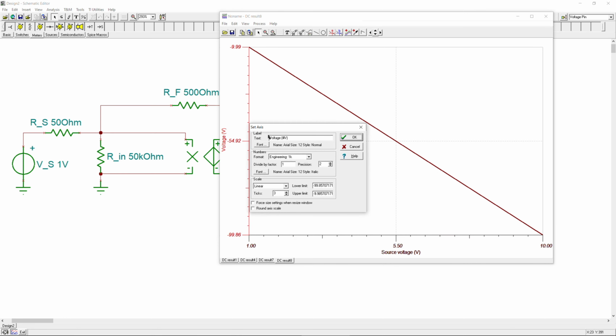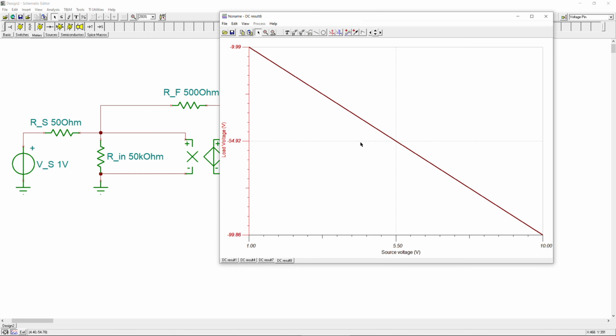And this is the load voltage. Okay, and you can see, if I just click on it with my cursor here, and if I now, for example, select 1, I get the value I already had also in the simulated result shortly. And also I can just look at maybe 5, and this is almost minus 50. For example, minus 50 over 5 is minus 10. So again, very close to minus 10 as the gain.